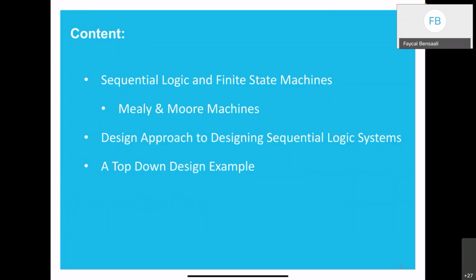So from the name of the circuit, finite state machine, it has a limited number of states. A counter is a very good example of finite state. If we have a 3-bit counter, we know it goes from 0 to 7. We know that if the current state is 0, the next state, when we talk about states, is the outputs, yeah?